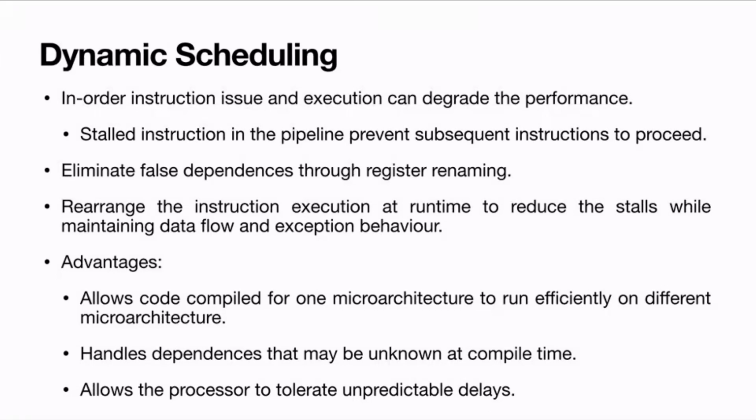For example, I mentioned the second point, register renaming. So we have to see how the register renaming is handled, how to identify dependent instructions, and how to select independent instructions and schedule them onto functional units. And if a functional unit is busy executing some instruction, what can we do with the next instruction? Where do we keep the next instruction? All those things will be handled in the superscalar processor, and that is what I'm going to explain in the next coming slides.